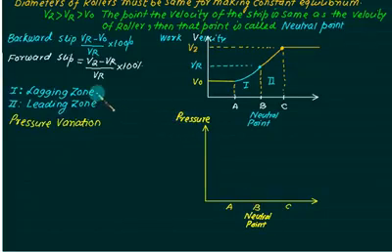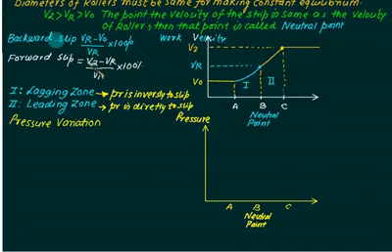As far as the lagging zone is considered, the pressure is inversely proportional to slip. And in the second case, the pressure is directly proportional to slip. So that is why we get a variation something like this. First the pressure will rise, so we start like this. It attains a peak value at this point and then the pressure will drop. So initially we have an inverse relation and then a direct relation. So maximum pressure will be approximately at the neutral point.